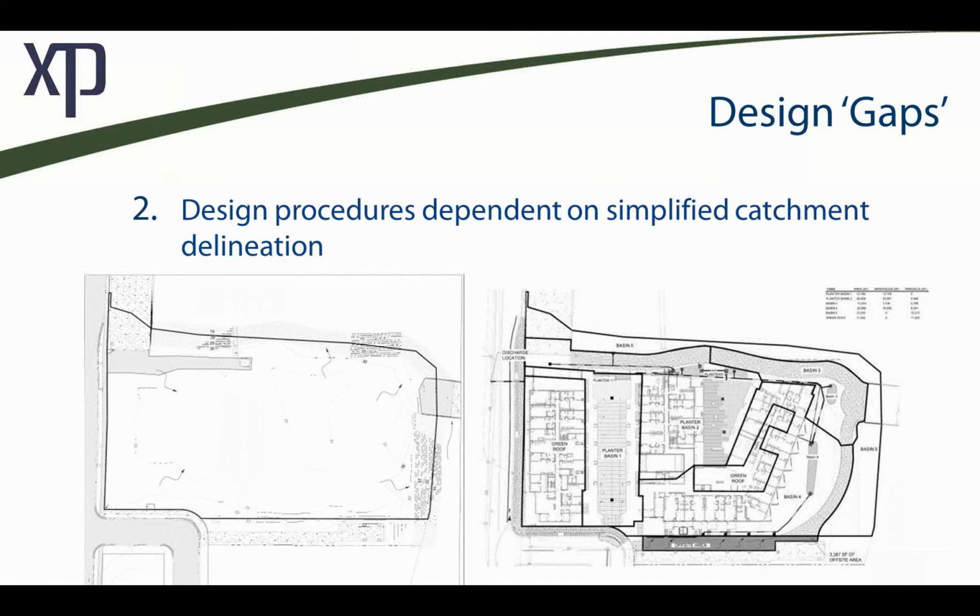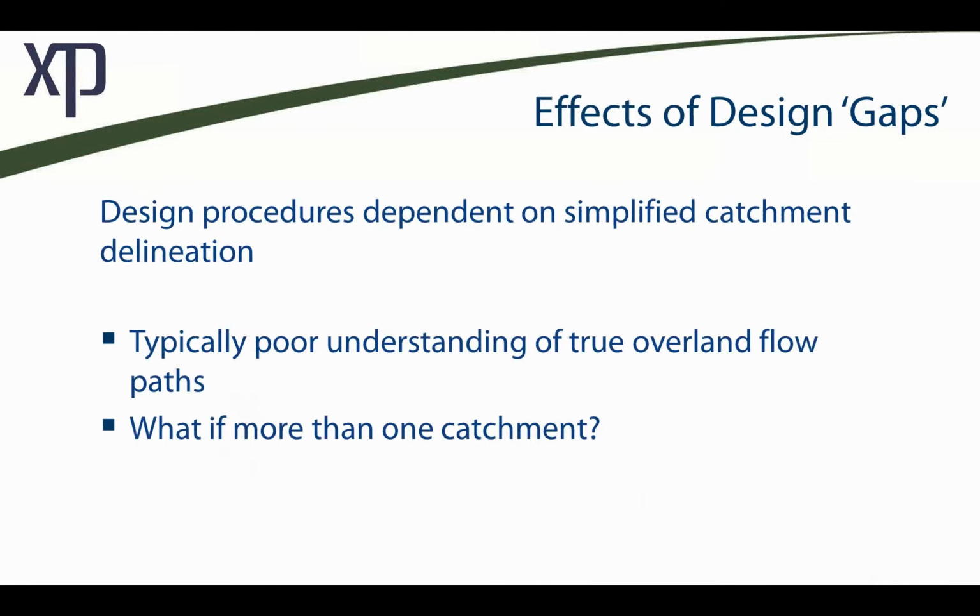Certainly, even if that was the case in our design scenario, where we're beginning to pour curbs, wow, that flow is going to be redirected, and likely we're going to have facilities cascade to one another, catchments combine in different facilities. Okay. Since we're limited with these spreadsheet tools, we're forced to simplify the catchments.